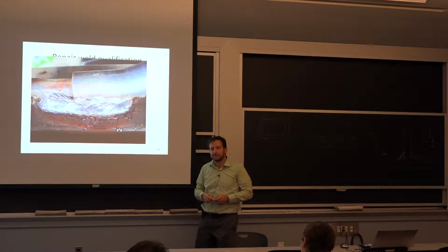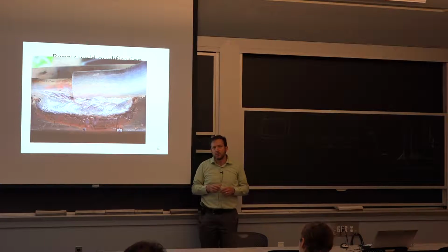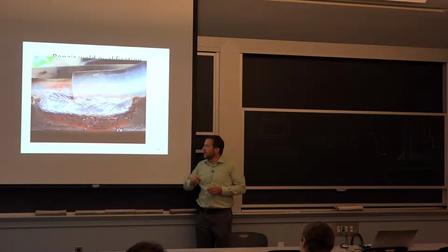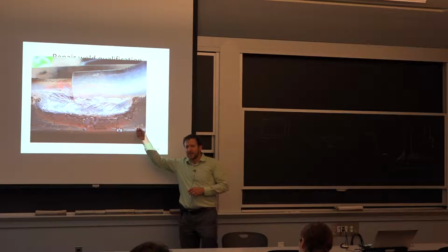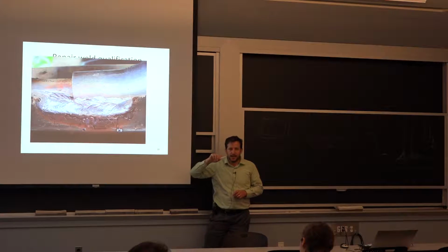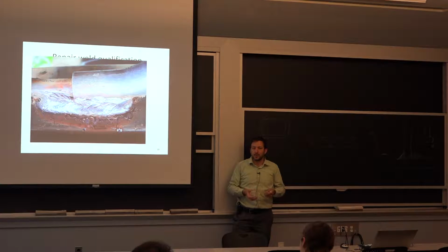Yes? What kind of welding was done here? This is just regular structural steel, so pretty low strength steel. Or, I mean, is it MIG, TIG? They were doing just regular stick welding. And the reason is the structure was galvanized, and they were cleaning up the galvanizing, but it was very difficult to make sure there wasn't any paint left or any galvanizing.